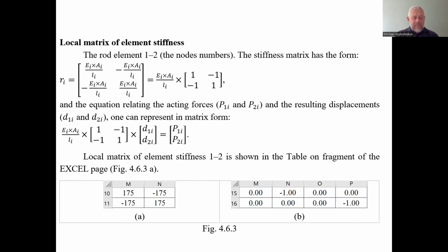The third type is the finite element hingedly connected at the beginning and embedded at the end. And the fourth type of finite element, like our definition shows, is the hinged connection of both ends. The size of the stiffness matrix for flat mechanical systems could be 2 by 2, or maybe 3 by 3 if we also consider the bending.